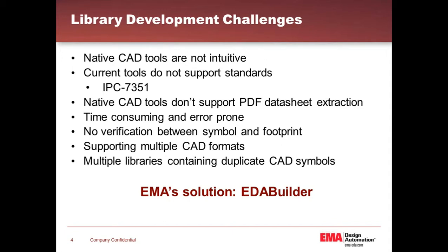Each of us have had our own methods for creating libraries in the past. When it comes to PCB footprints, there are times when you might call up a PDF drawing, get the XY coordinates there, and just enter the XY coordinates into your PCB CAD library tool to position those pins. That's fine for a 20-pin DIP or something like that, but when you get into parts that have 500 to 1,000 pins, that is very time-consuming and, like I said, very error-prone.